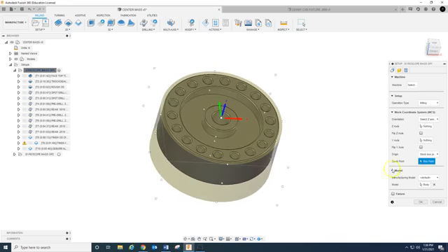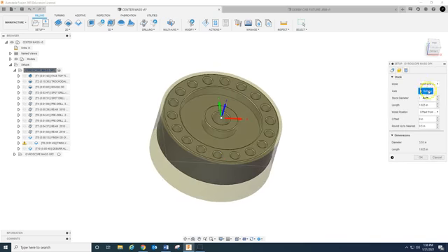So then you come over here, you pick your stock. You say, how big is your stock? If you notice, I put in 3.55, but I told you that the material was 3.5. This is just me giving the students, myself, whatever, a little bit of wiggle room to where if their offset is tweaked a little bit, let's say they forget to put in a tool diameter or something like that, this will give us a little bit of cushion.